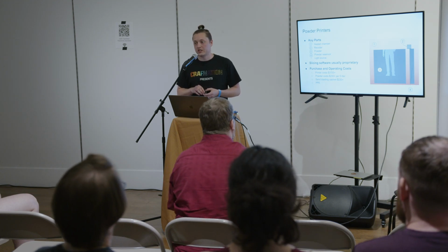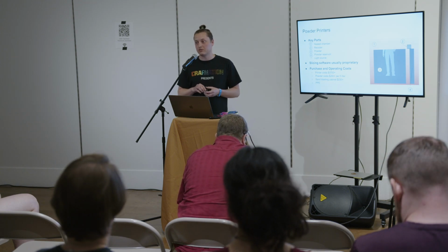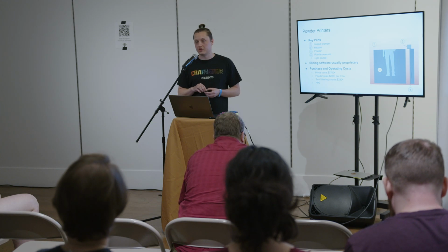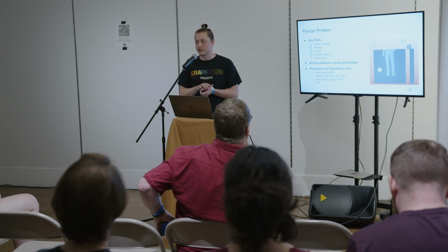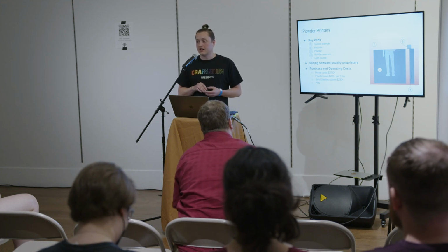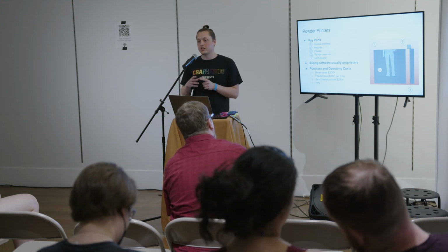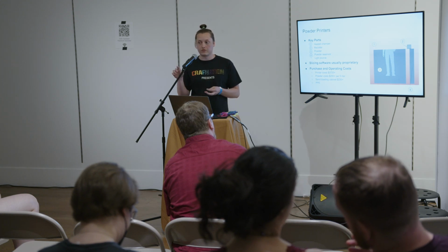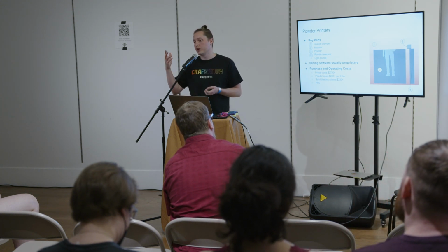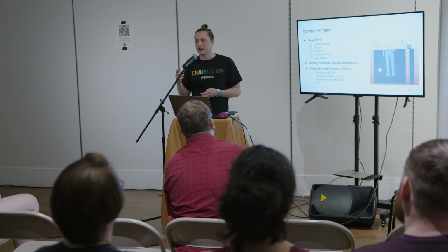Yes, so injection molding cost is extremely high. Generally to make an injection mold, you have to use a more traditional manufacturing method, which can be extremely expensive, especially if you're looking for super high tolerance parts. Resin is not nearly as robust. Usually you use something like aluminum or steel for injection molding, and resin won't hold up. You won't be able to get as many injection shots out of a resin mold.